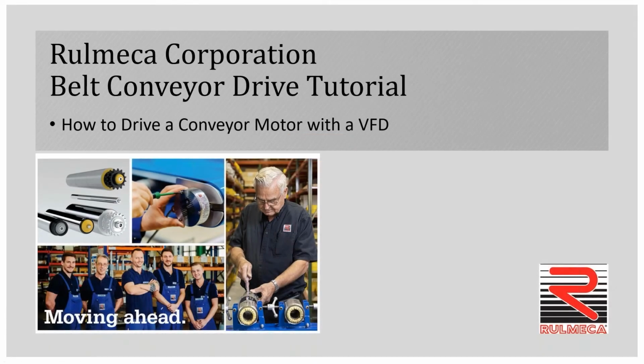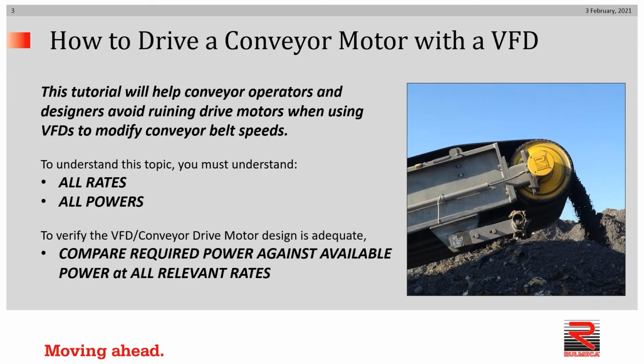To understand how to properly apply a variable frequency drive when attempting to use the device to modify conveyor belt speeds. This tutorial will help conveyor operators and designers avoid ruining drive motors when using VFDs to modify conveyor belt speeds. A proper understanding of this topic requires that you understand all rates and all powers. And to verify that the VFD and conveyor drive motor combination is correct, you must compare required power against available power at all relevant rates.